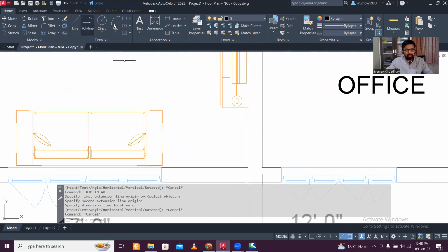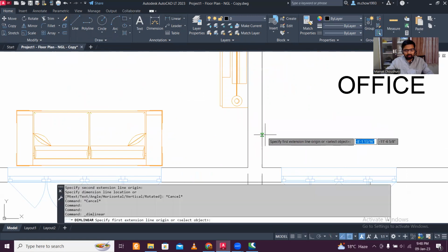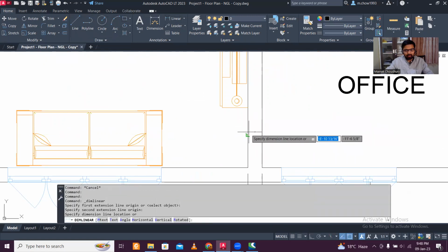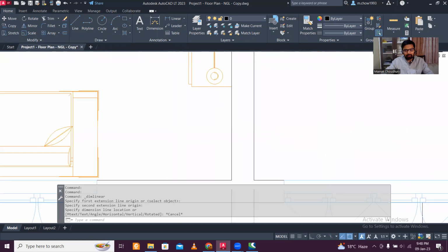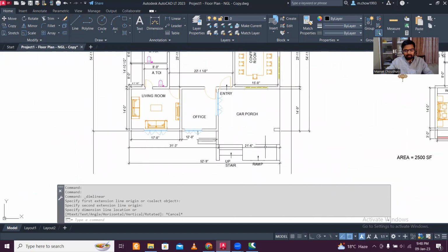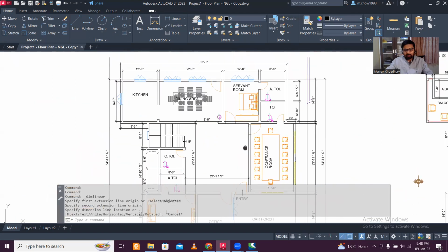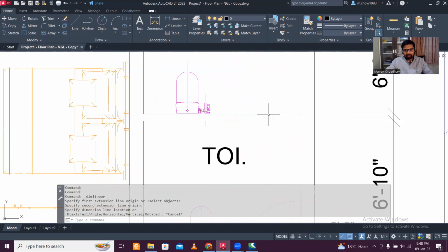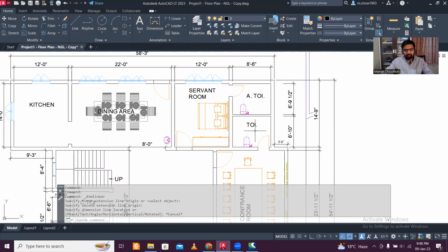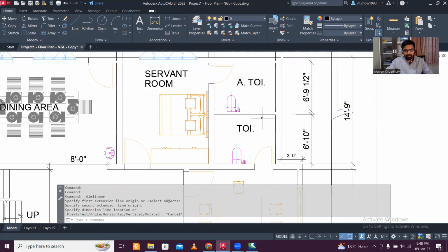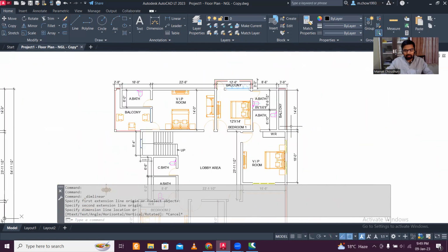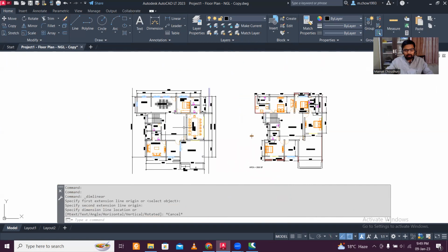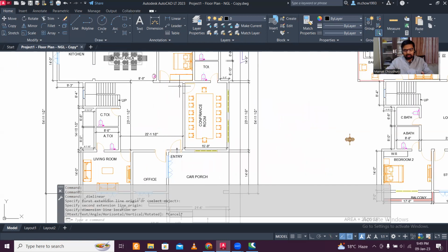And interestingly, they have given the same width. There are no half-inch half walls. All walls are the same width. So while we apply the member loads, except this toilet portion, we need not bother to give this anyway. This is a very small distance. We can ignore this particular beam also. So apart from this, all the member loads which we'll consider will be calculated as per this.